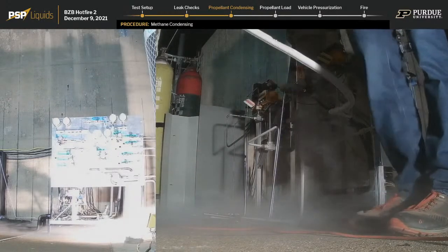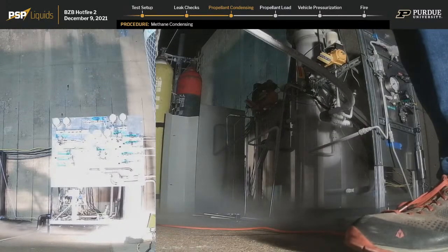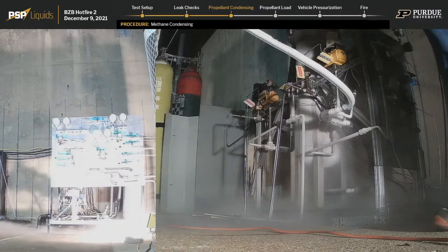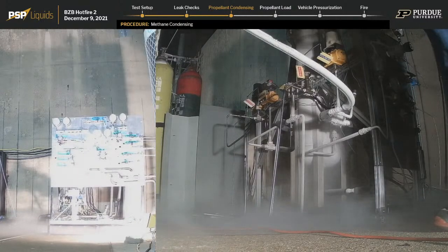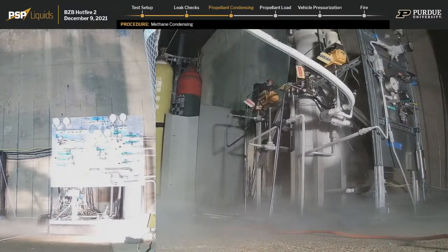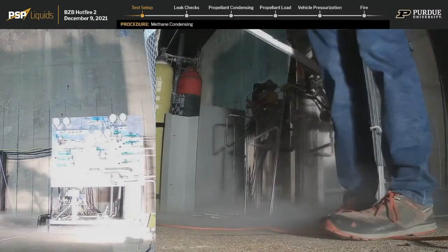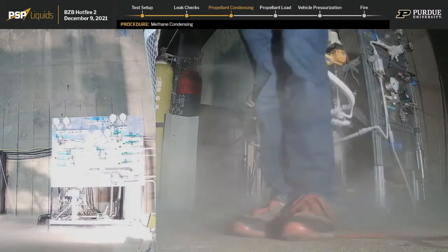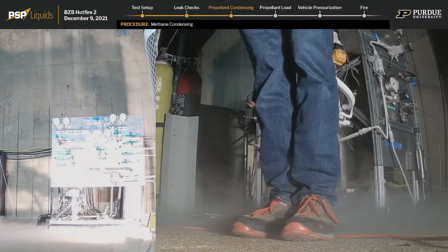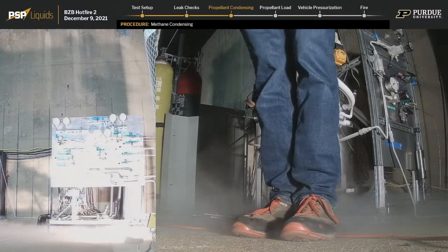So, we are partially through this dewar swap now. Just to reiterate, why do we do a dewar swap? We do a dewar swap to make sure that we have adequate liquid nitrogen levels going into propellant load, and so that people do not have to be on the courtyard for the safety critical parts of the test. Right. And as you may have noticed, we are just dumping liquid nitrogen out. So this first dewar is entirely dedicated to just chilling the overall system. Yes, and chilling is probably the longest part of the system going into propellant load at this point. The dewar is pretty close to ambient right now. We will quickly head into propellant load, and following propellant load, we will proceed immediately into go ahead and load.